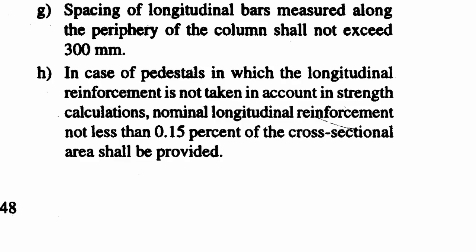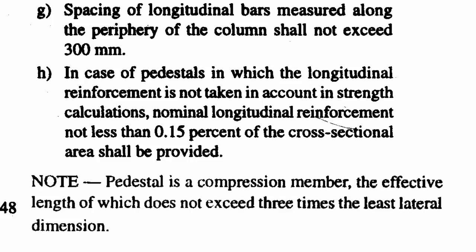Now, the last thing it is telling is in case of pedestals. As you have seen, what is a pedestal? Here you see the note is given. What is the definition of pedestal? Pedestal is a compression member, the effective length of which does not exceed 3 times the least lateral dimension. Very clear. The definitions are also given in the code.